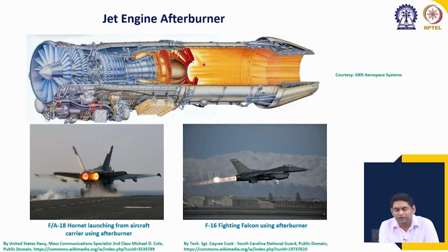Here there is no turbine after this, so we can take the temperature to say 2000 Kelvin, also with suitable lining material for the bypass, for the afterburner and for the nozzle section. So, this high energy fluid can generate very high velocity exhaust gases which can increase the thrust, but this